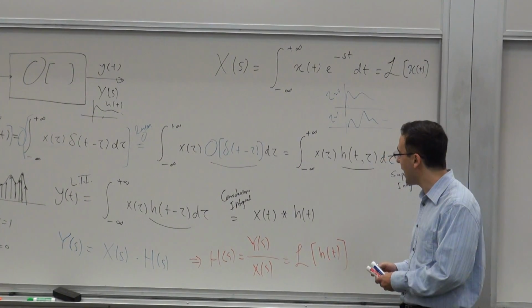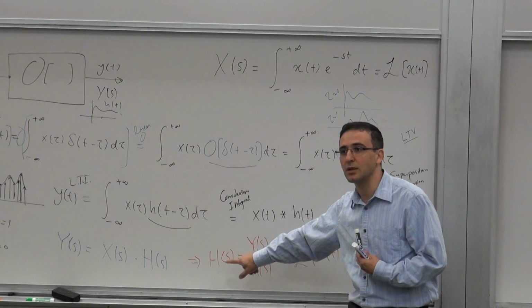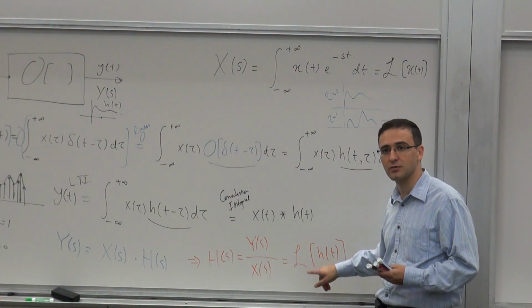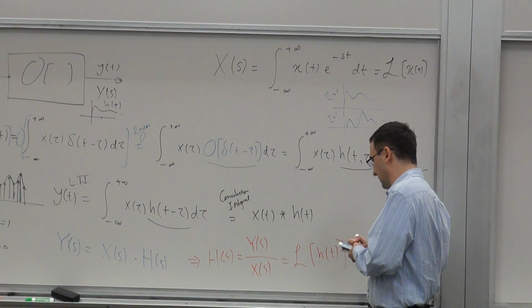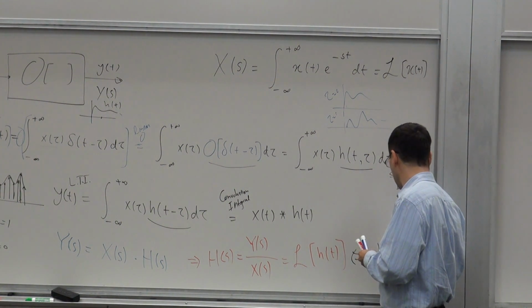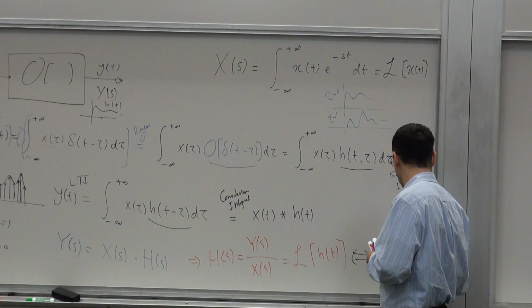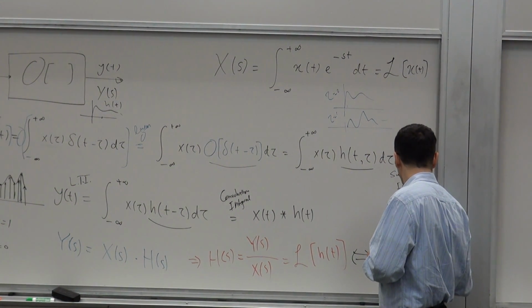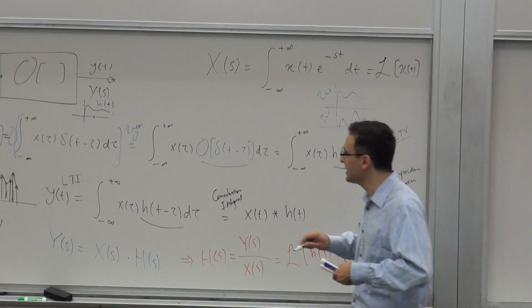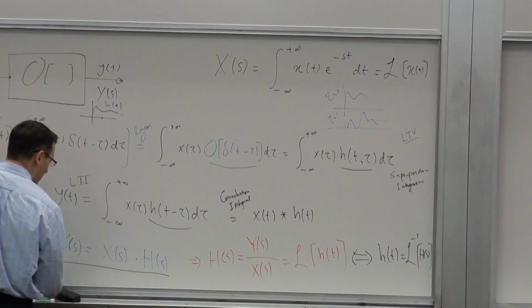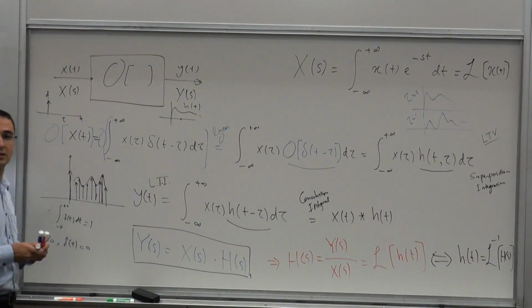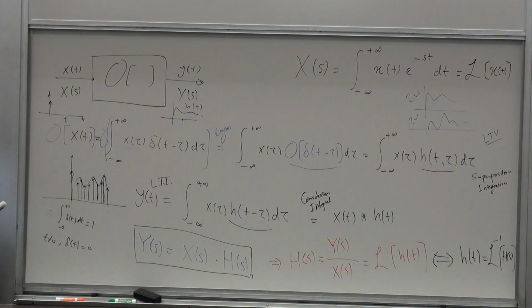And the good thing is that now if you have your transfer function, which is something a lot of times for the kind of circuits that we analyze, easier to calculate than the direct impulse response, you can easily calculate, of course, the impulse response, which basically, the time domain impulse response would be the inverse Laplace transform of the transfer function. Now, this is a very important thing. Basically, this is the important result that comes out of this discussion, which is something that you already knew probably, most likely. You've had it in your previous courses, and this is nothing but a review.